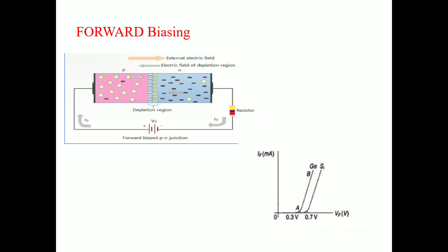The diode conducts when the depletion layer disappears. The depletion layer disappears when you increase the forward voltage greater than 0.6. Here I am using a silicon material. When the forward voltage is greater than the barrier potential, my depletion region disappears or is eliminated. A small amount of milliamp current enters the material. So current is flowing. If you note down 0.6, a small amount of current.